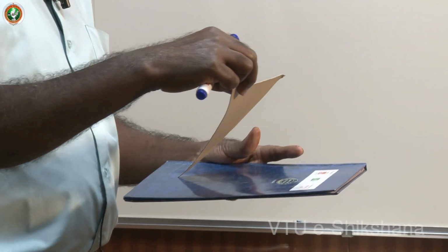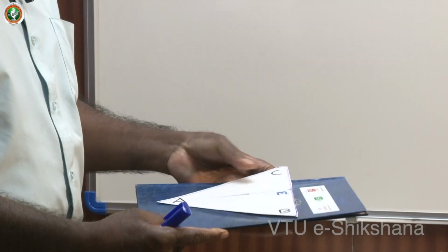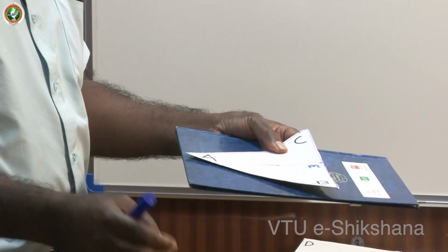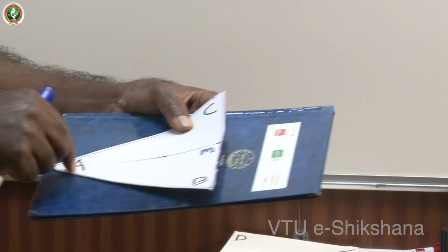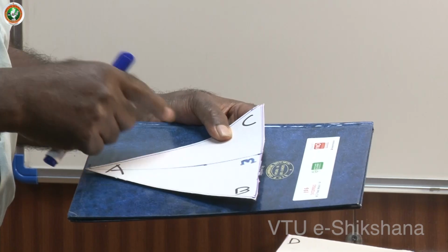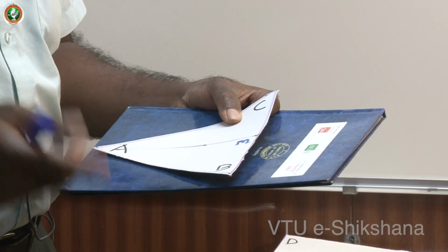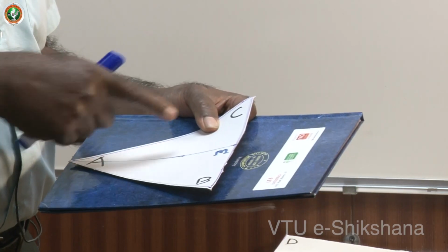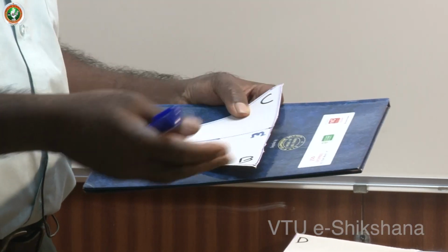First position, second position, third position. I will repeat. First position, corner condition: you see that in a perpendicular line the corner should be placed here, and then see that this median is parallel to VP, or the opposite side is perpendicular to VP. How do you start working? You should start from this. Easy. Start with a side which is perpendicular to VP, to the right side.